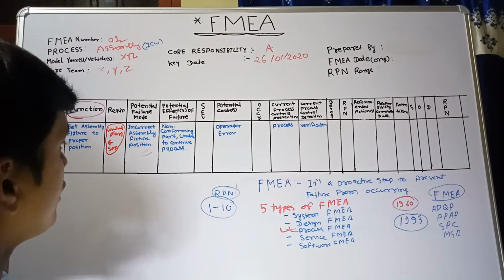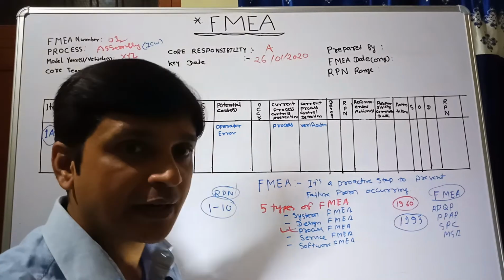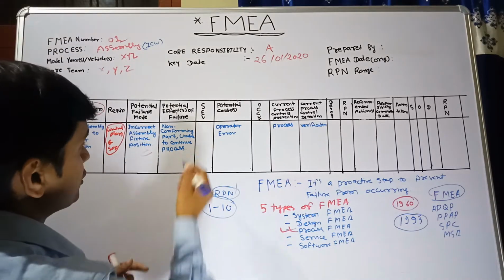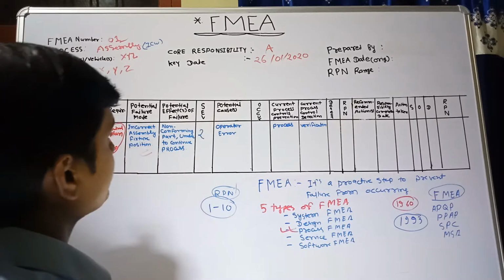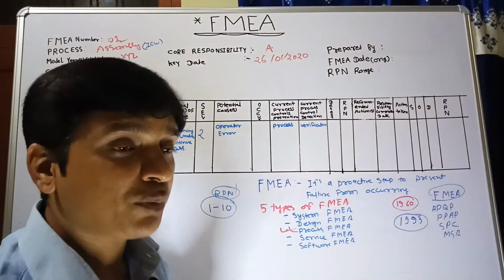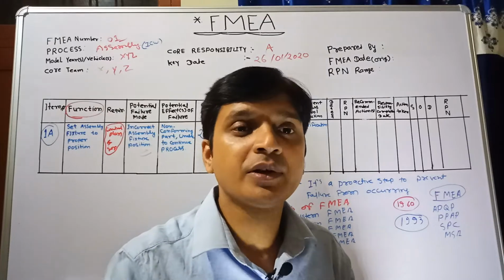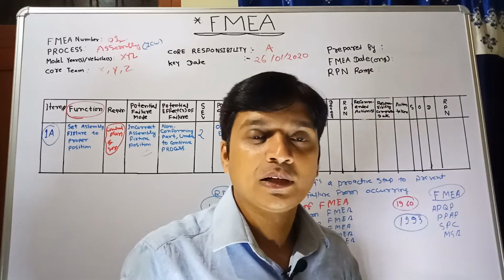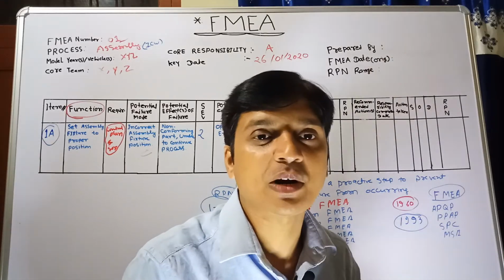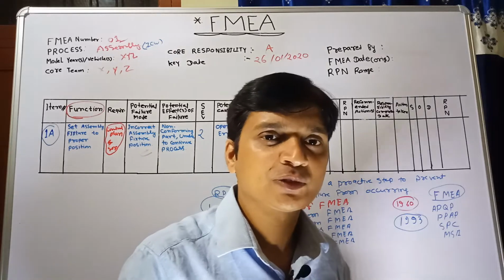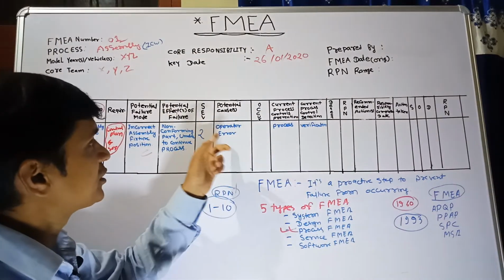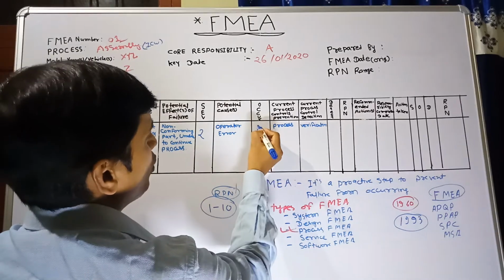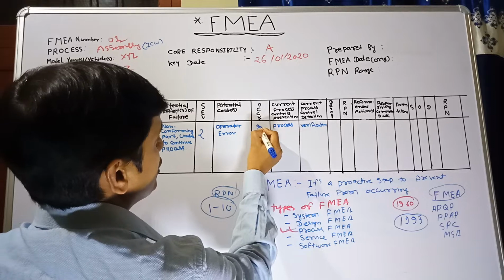At this situation your product will be non-conforming, so it directly affects the customer. So the severity will be 2. And what are the potential causes why the non-conforming part will be made? It is the operator mistake. Why? Because the operator did not take a first part approval, did not do a job setup, everything. So that operator error is the potential cause of the non-conforming part. At this situation occurrence is 7.